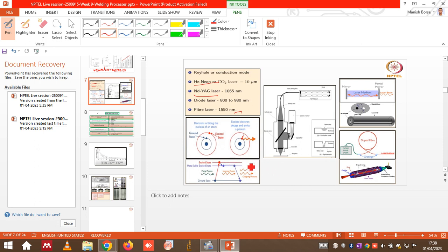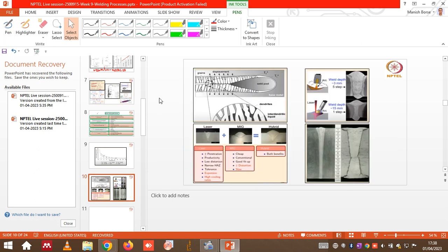Okay, so this is just basic regarding the laser welding processes, and we have also seen in the slides from the regular lectures that in laser welding processes we generally form a teardrop kind of nugget. As this is the welding direction, the solidification will take place behind the source, or surrounding the nugget area, and this will generally be columnar type.